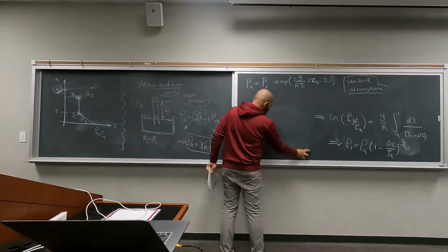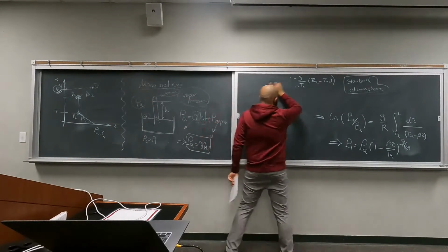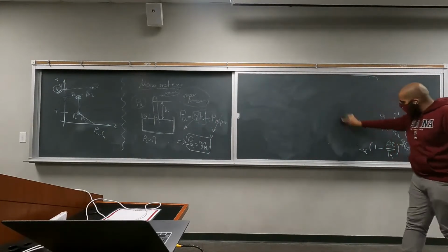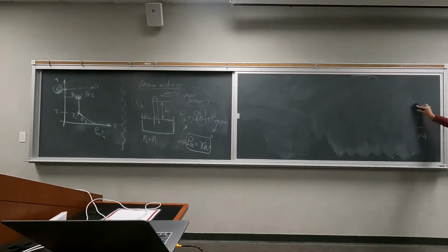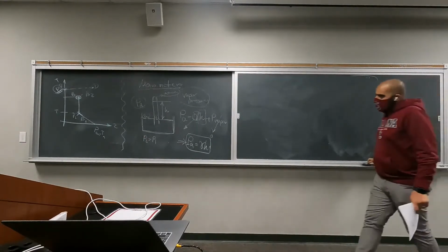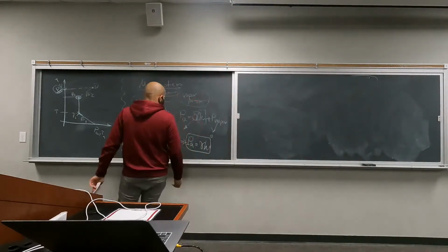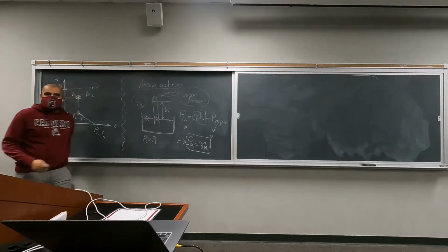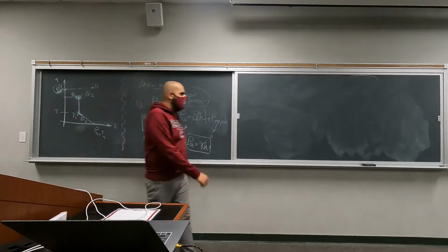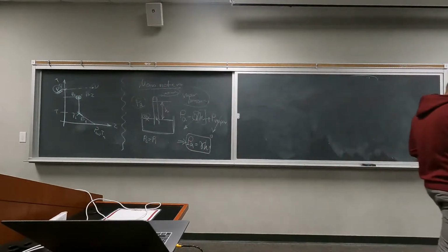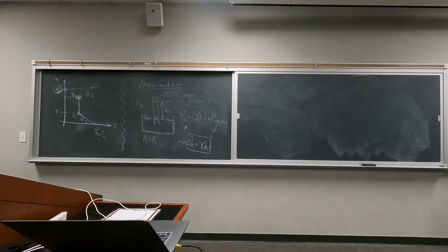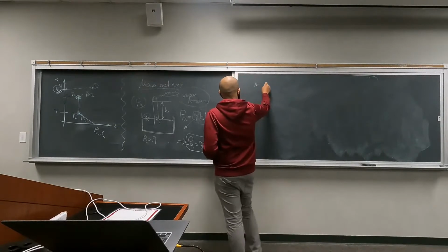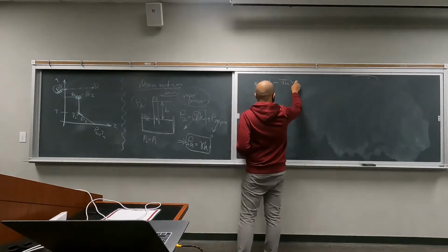This opens up the way for other pressure measurement devices, all of which work based on the same concept, that the pressure at 2 points that are at the same height are essentially equal. We have the piezometer tube, which is exactly the same thing, but we also have this thing called the U-tube manometer.